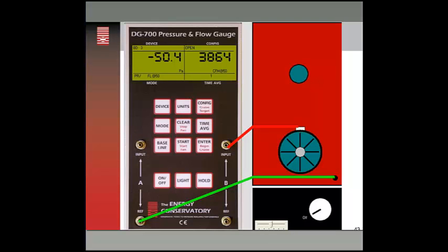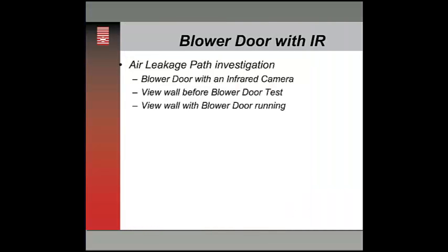And basically, blower door test, most of you know. Blower door test, pretty straightforward. Depressurize the building to minus 50 pascals, and then take your CFM at 50 times 60, divide by volume. You got your ACH 50.